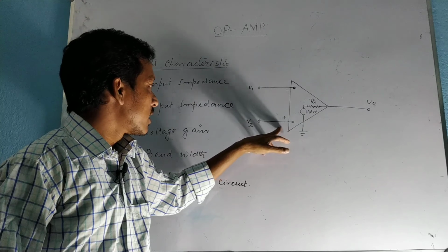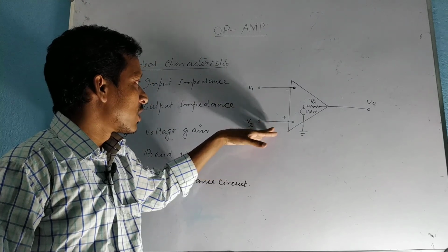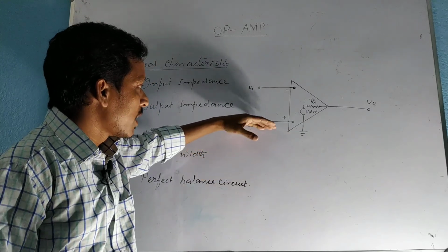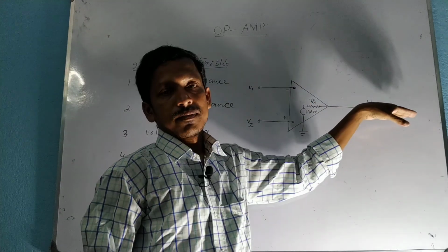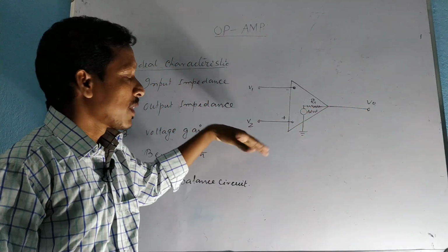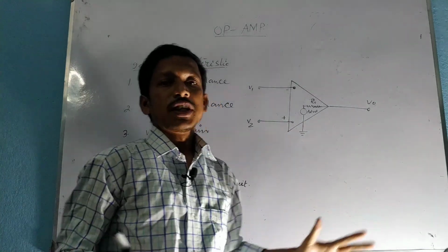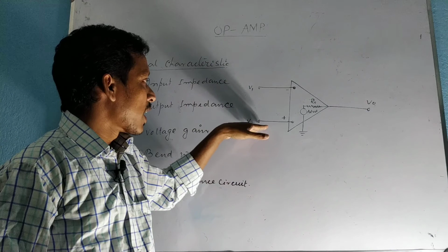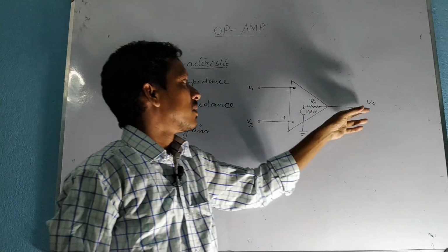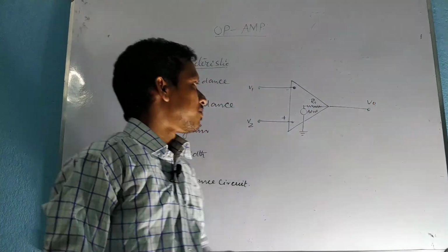Now the other input is called the non-inverting input. If we apply input here, no phase change occurs. If we apply a positive signal, then we will get a positive signal. There is no phase difference between the input applied at that input terminal and the output.